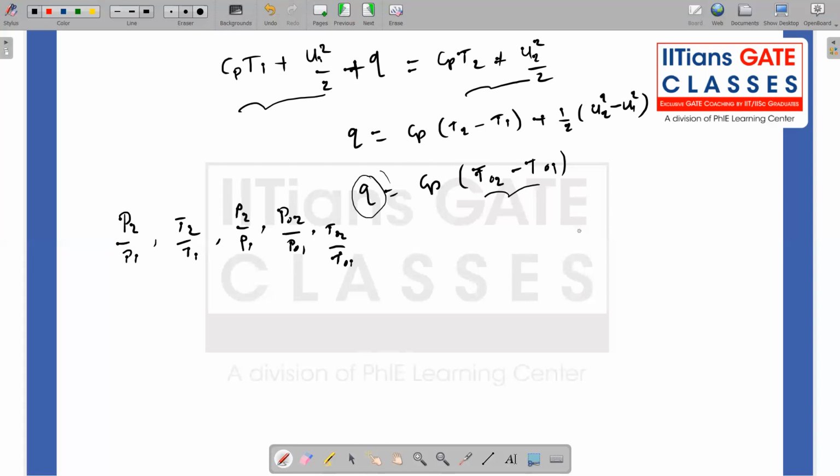So for that, I am going to alter my governing equation a little bit. So we have the rho u square form. What I'm going to do is use the definition of Mach number. Mach number is nothing but u by a, the local speed to the local speed of sound. So u I can write in terms of Mach number times the local speed of sound.